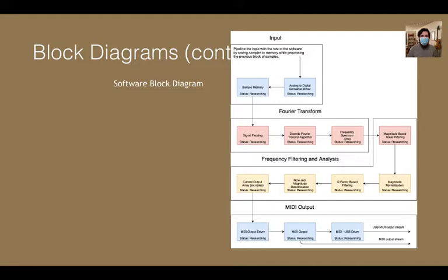So from there, another omission we had is we omitted the magnitude-based noise filtering, where the initial idea was to cut out any very low magnitudes that couldn't be notes or harmonics in the first place. That would just be noise, but we found that we are getting some harmonics that were very, very low magnitude and some noise that were louder than those harmonics. So we found that we did need to use those harmonics and we couldn't cut them out.